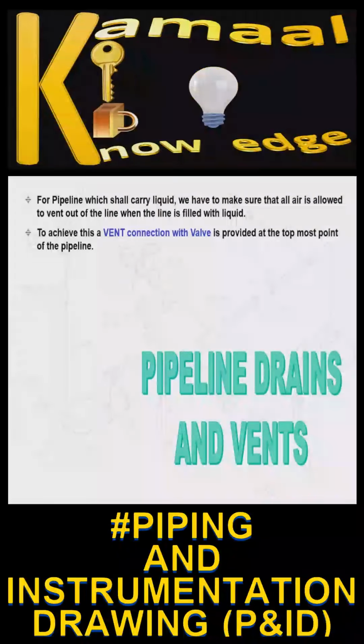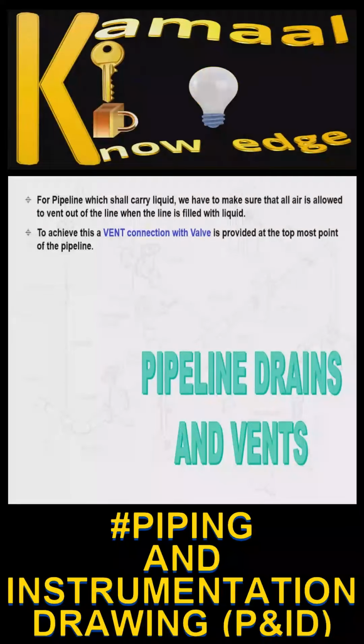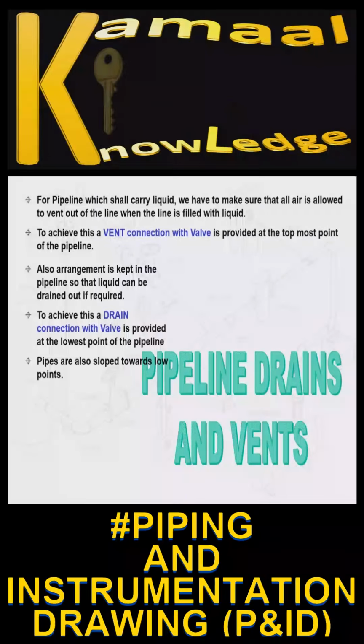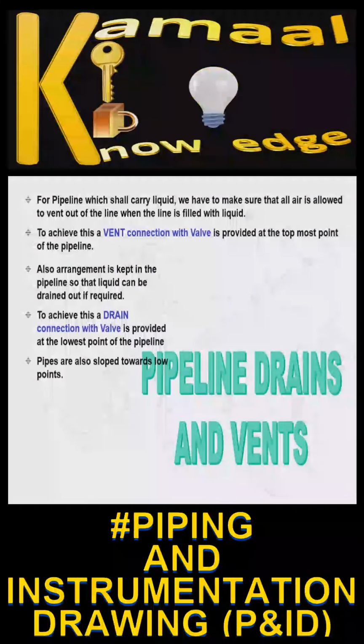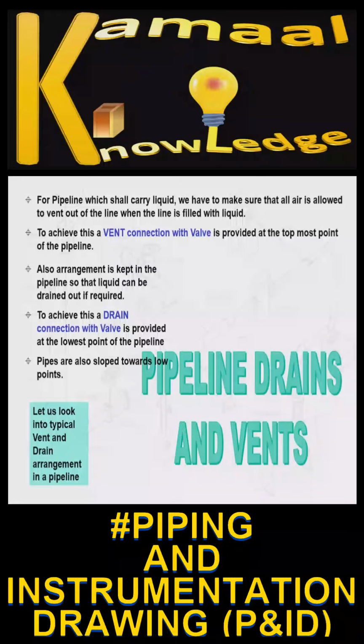For a pipeline which shall carry liquid, we have to make sure that all air is allowed to vent out of the line when the line is filled with liquid. To achieve this, a vent connection with valve is provided at the topmost point of the pipeline. Also, an arrangement is kept in the pipeline so that liquid can be drained out if required. To achieve this, a drain connection with valve is provided at the lowest point of the pipeline. Pipes are also sloped towards low points. Let us look into a typical vent and drain arrangement in a pipeline.